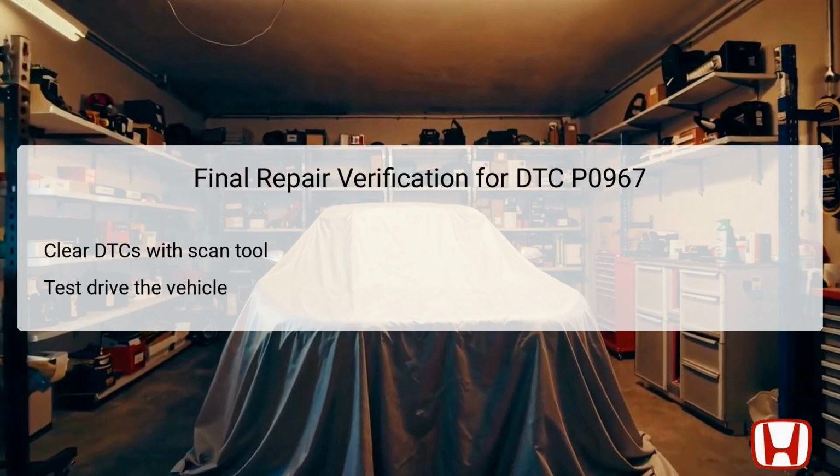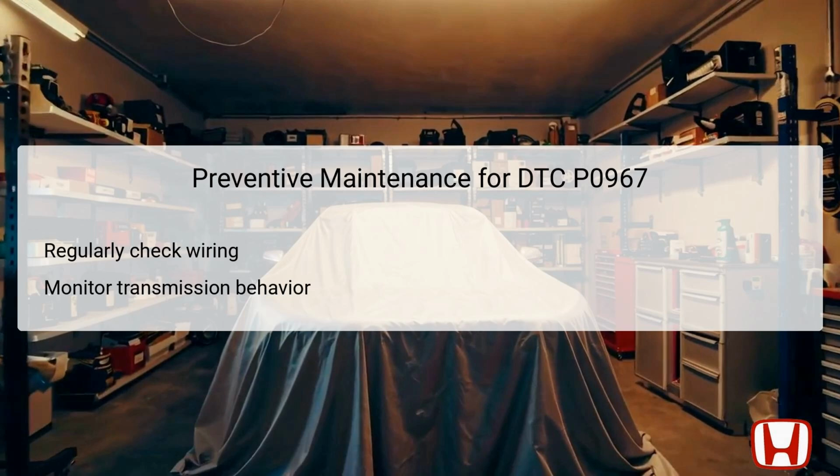If the DTC does not reappear during this process and the vehicle operates as expected, it can be concluded that the issue has been successfully resolved. To prevent the recurrence of issues related to DTC P0967, proactive maintenance practices should be adopted. Regular inspection of the wiring associated with the CVT-driven pulley pressure control solenoid is essential.